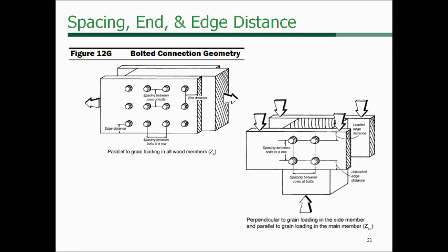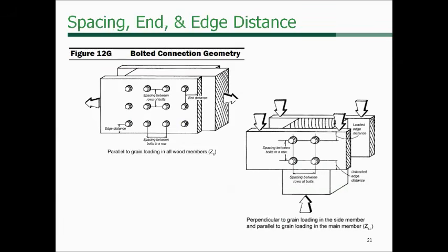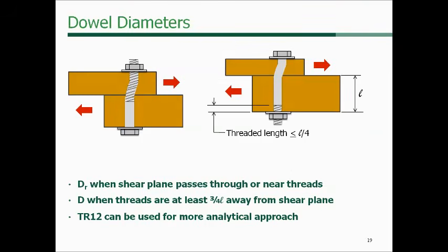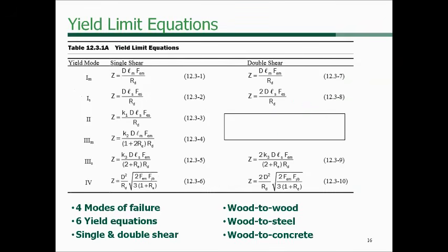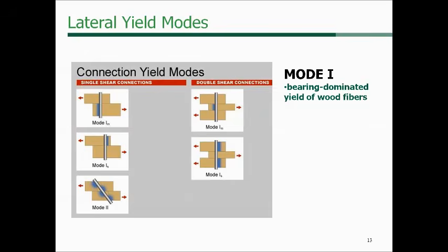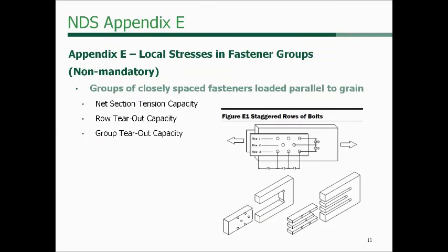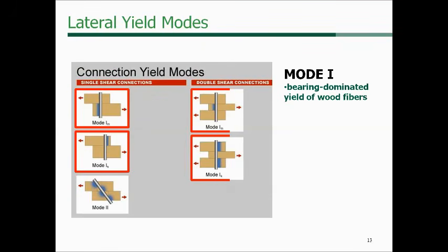Okay, great. We had another one. So we talked about that 5-inch maximum row spacing for bolts. When you have 3 rows of bolts, is that 5-inch spacing reflected as an outside to outside dimension, or is that the spacing between the individual rows, rather? Great question, and the short answer is it's the outermost rows.